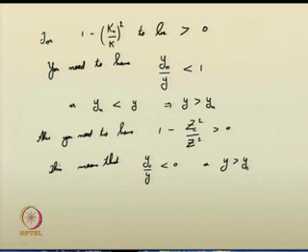You can now understand that. So, this means your depth of flow should be greater than the critical depth. This implies subcritical flow, right. Also, your depth of flow should be greater than the normal depth, right.